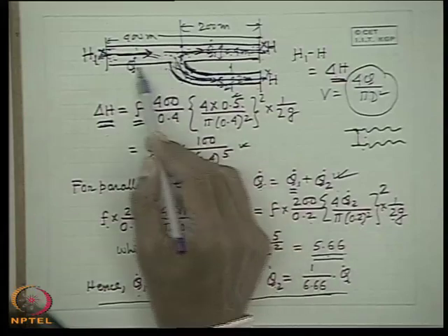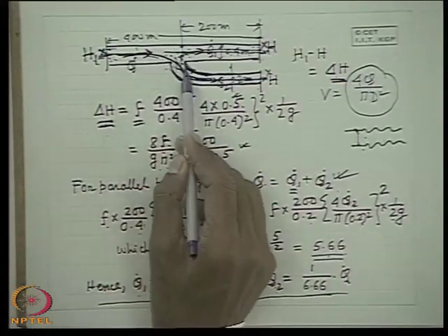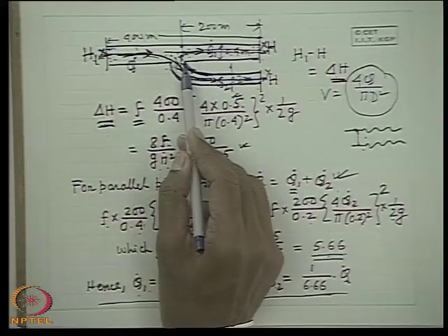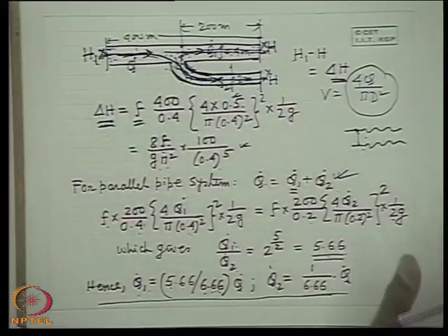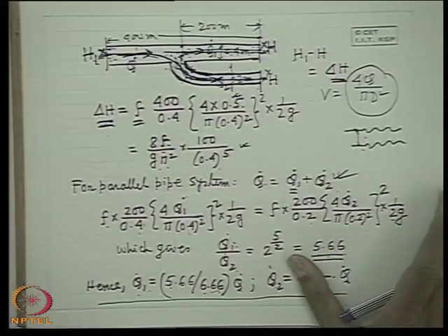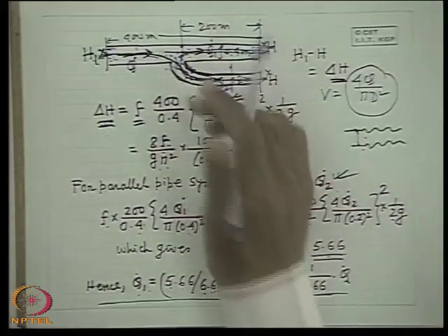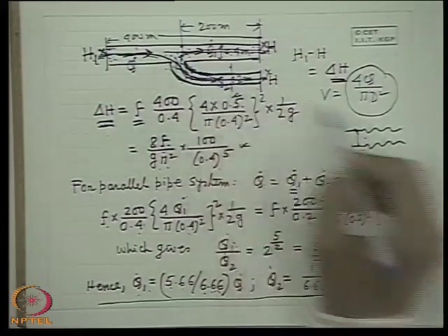Losses, very correct. There will be some loss. Definitely the fluid flows like that. Practically a pipe cannot be made parallel like that. It cannot be superimposed on that. So there will be a bend and all this. This we neglect because of the lack of data. We are not told. That can be added, considering a bend loss for whose coefficient is this.